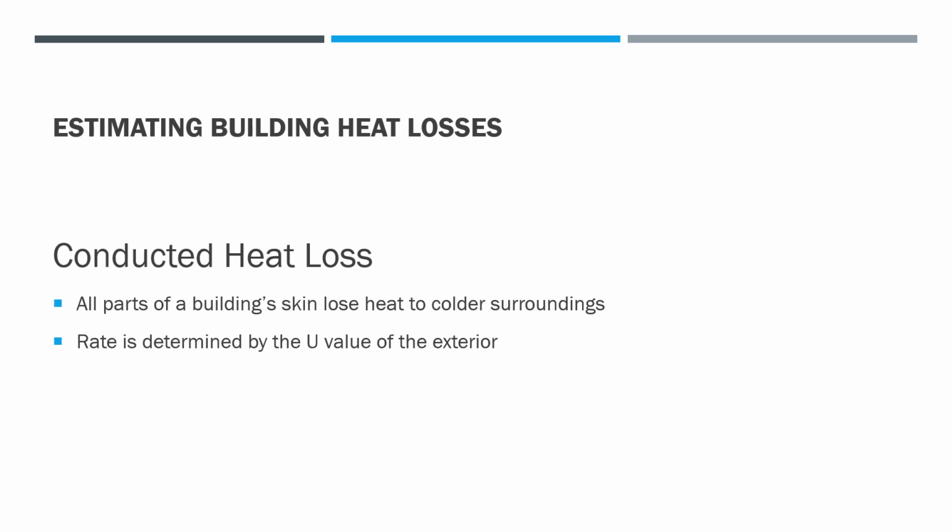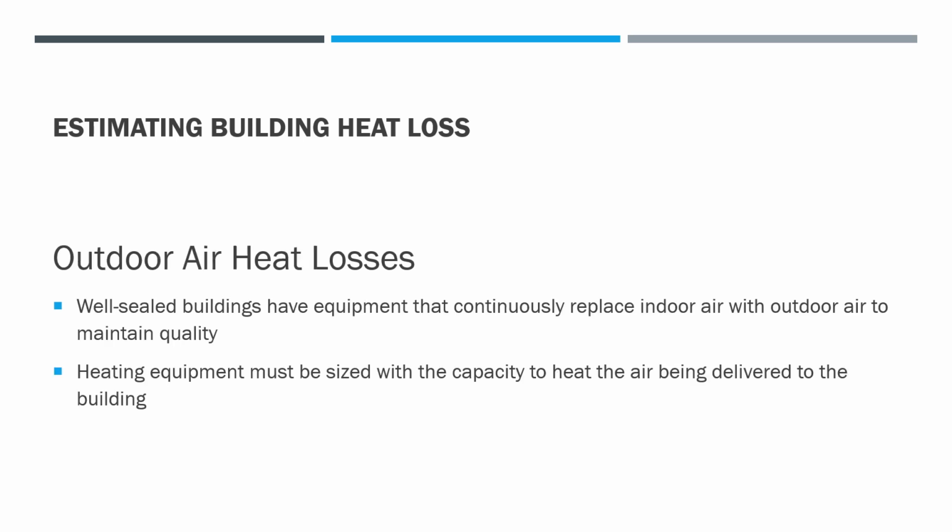And how do we find the U value? We have to find the R values, which is what Dr. Kosak talked about this week. It's 1 over R1 plus R2 plus R3, etc. If you add up all the R values, you get the R total, and then you just convert it using the reciprocal. So that's how we do it. I would put these equations in here, but I somehow forgot to do that. If you want to go back and rewind it, you're more than welcome to.